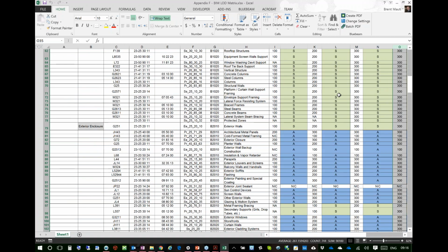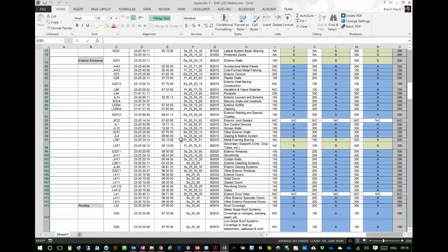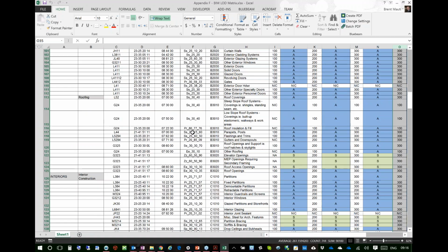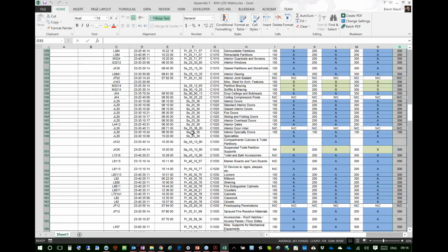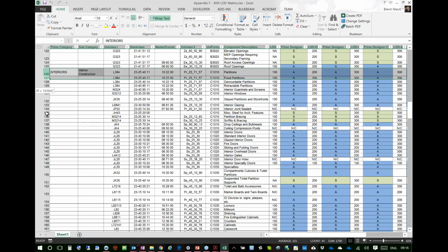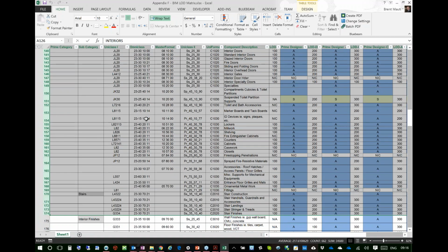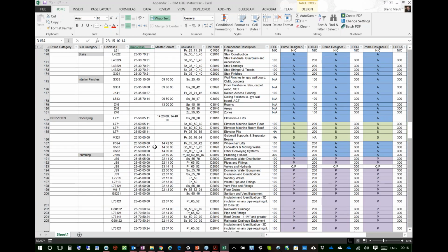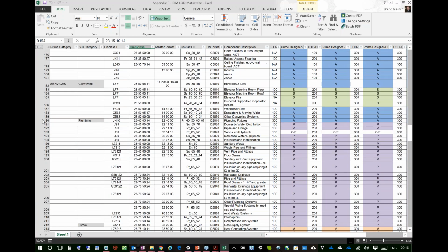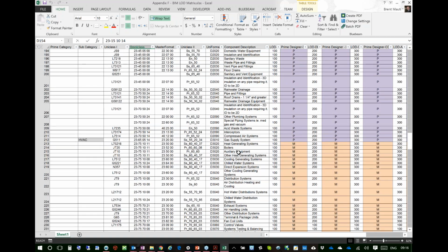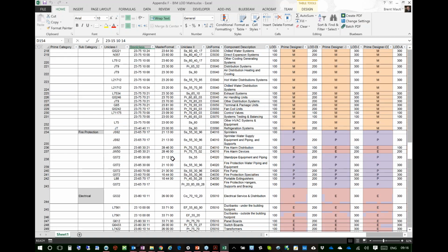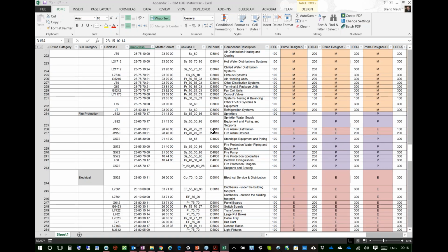So with that, you go down the LOD matrix. What we tend to say is, if something doesn't apply, you delete it. So let's say we're not modeling any interiors. I would hide or delete the interiors from my LOD matrix. The services, plumbing services, is where mechanical will define to what extent they're running their components.